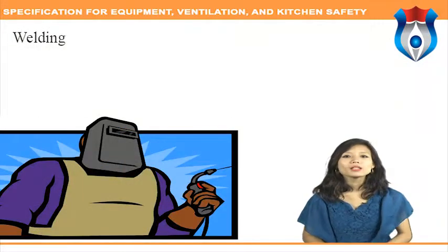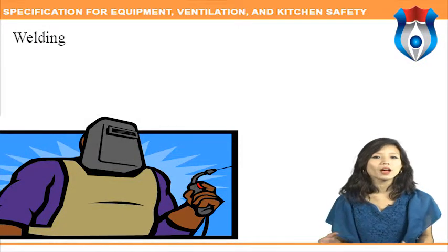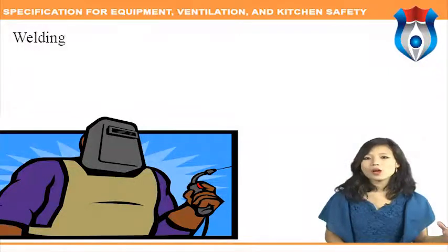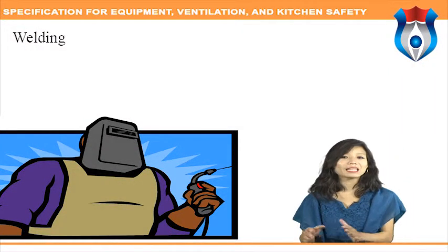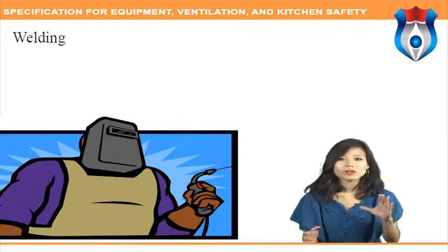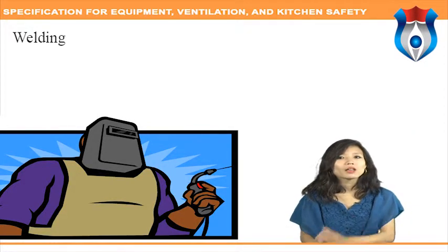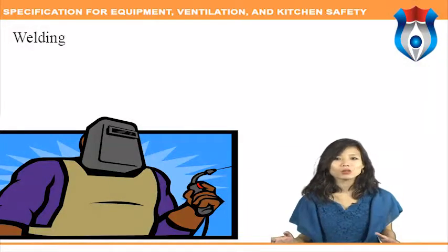Welding. Welding is the preferred method of joining sheets of metal that cannot be formed into the desired shapes. Heliarc welding is used on stainless steel if there is sufficient thickness of metal. Heliarc welding utilizes an inert gas as a flux, resulting in a very smooth and strong weld. Heliarc welding is preferred for all kitchen equipment with food contact zones.